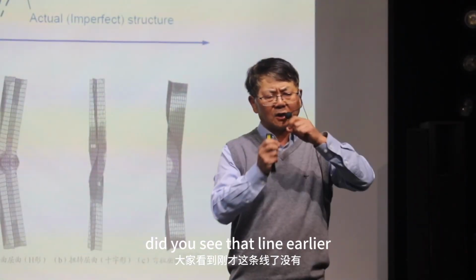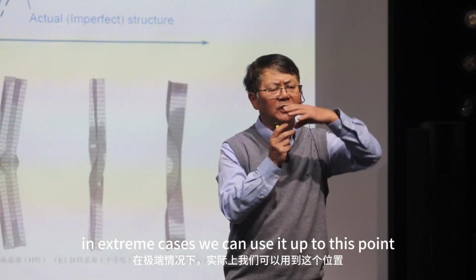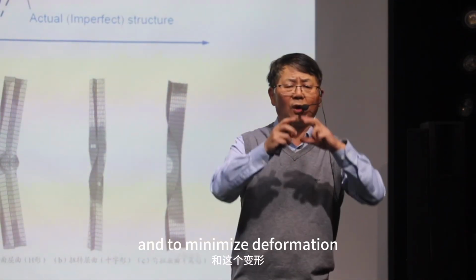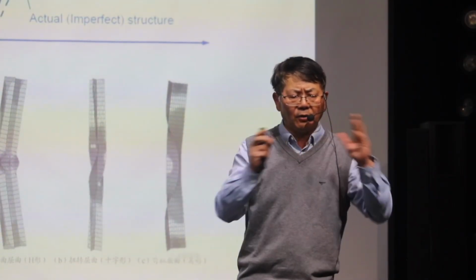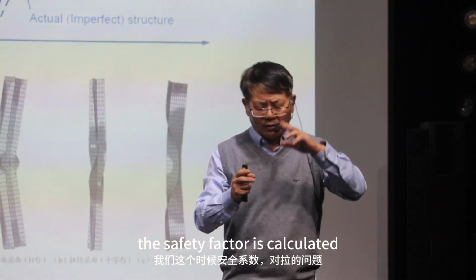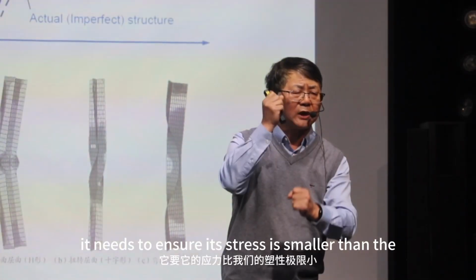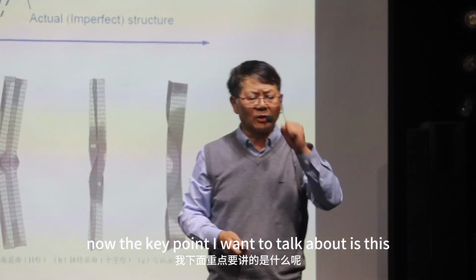In extreme cases, we can actually use it up to this point. Did you see that line earlier? In extreme cases, we can use it up to this position, so it will not break. However, in order to maintain the integrity of the entire structure and to minimize small deformation, we cannot use it to that point. This is how it works. Remember the safety factor. For tensile issues, the safety factor is calculated based on uniform stress. It needs to ensure its stress is smaller than the plastic limit. That's sufficient.